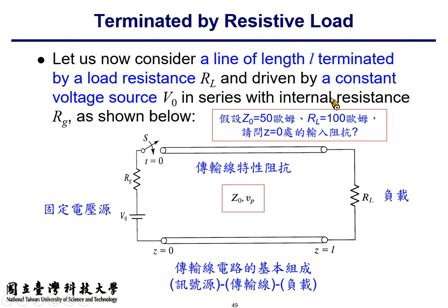Signal goes into the transmission line, voltage and current flow into the line, and at a certain point, with some time delay, it will reach the end of the transmission line. Because of the mismatch at the end, 50 ohm here and 100 ohm there, you will have the so-called reflected signal, the negative going signal.